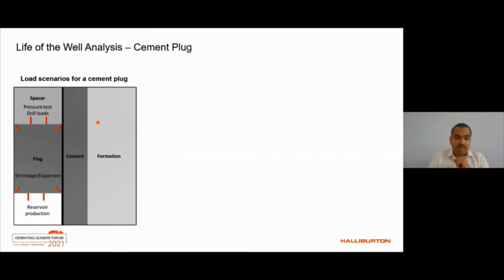These are the potential load scenarios that a cement plug can experience. Are these all? Not really. These are some of them. Like there could be hydrostatic from the spacer or mud above it. There could be a pressure test that happens once the plug is set. Potential drilling loads, if it's not an abandonment plug, let's say it's a kickoff plug.